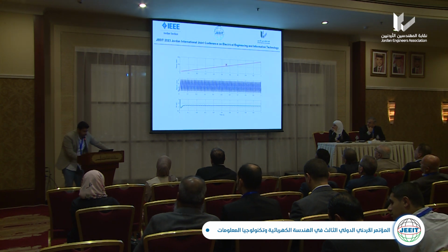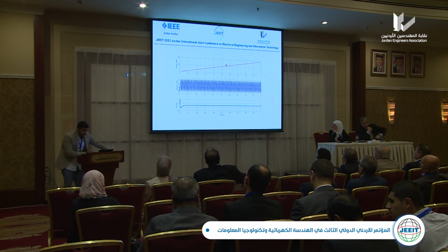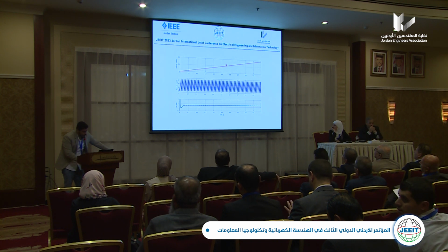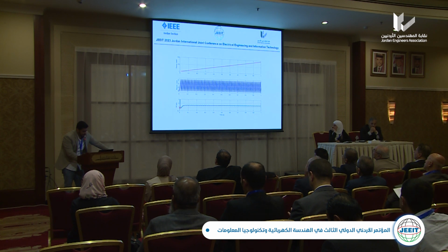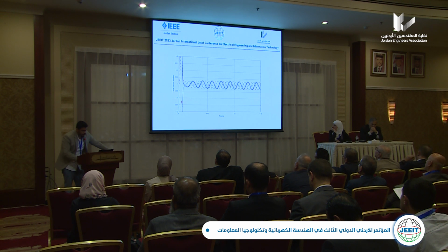We integrate the output omega that I mentioned earlier in the control system, and the sawtooth signal enters the reset toolbox, giving omega phi that we use in the control equations. These are the three-phase signals for the PWM, pulse width modulation, in order to control the switching of the inverter.